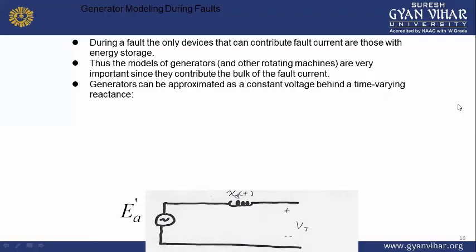This reactance, when combined with the leakage reactance XL of the machine, is called the synchronous reactance XS, which is nothing but Xd, the direct axis synchronous reactance in case of salient pole machines. The armature resistance being small can be neglected.